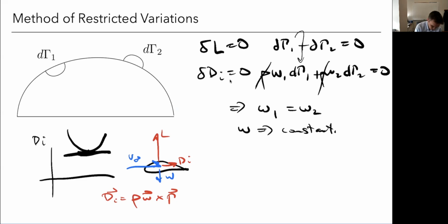And it kind of continues along the same direction all the way around the wing. So if you put your thumb in the direction of the arrow and curl your fingers, that points in the induced velocity. So there's downwash here in the middle, right? This one, I put my thumb, it's pushing down, forward is pushing down, right? They're all pushing down.